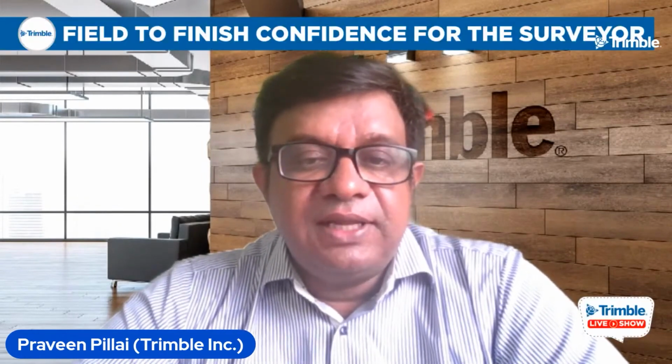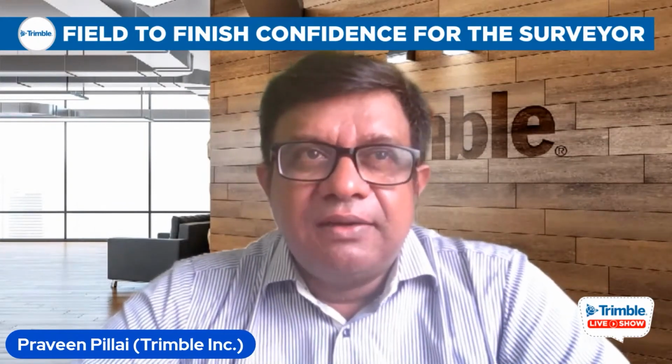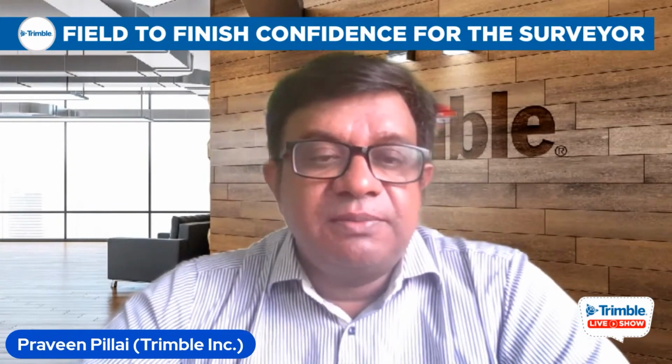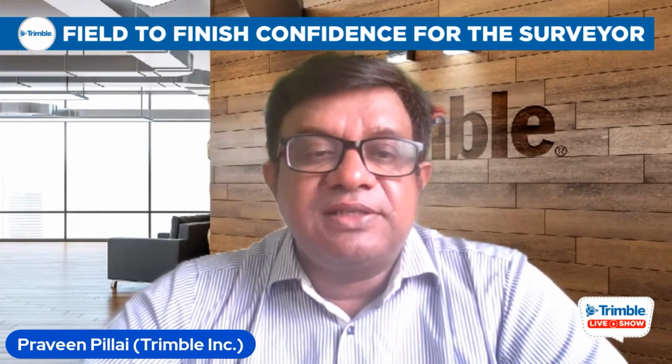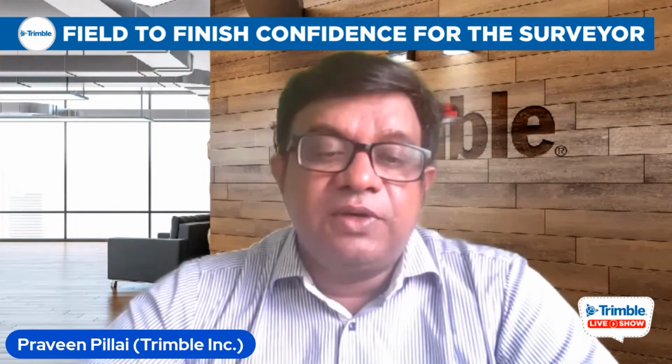Or if I want to send them some data which needs to be staked out in the field, some road design data from TBC itself, I import the data, I process that, and I export the design file to the field seamlessly. Once my field crew is in the field, he'll get a message that some data has come in. He can just import that data, and then your design data is available in the controller in the field, and you can do a stakeout in the field.